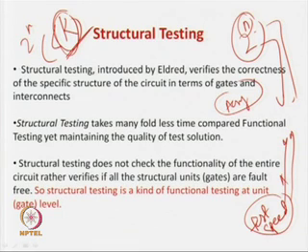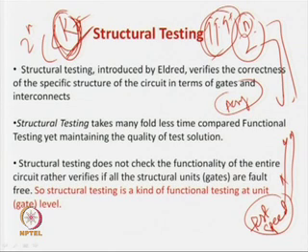Now, you have to find out the accuracy, that is, what wrong you have done, if there is any case where you have shipped a faulty circuit telling that it is normal. That is called inaccuracy in testing. But if you look at history, people have found that there can be very good strategies of determining this k number of test patterns where the accuracy is very high, even as high as 99.9% plus. That was a very surprising and nice discovery, in which people found that there exist strategies to find k test patterns, where k is much less than 2 to the power n, and still your confidence or accuracy in testing is as high as 99.9% plus.